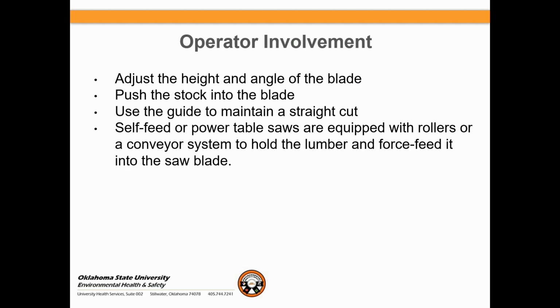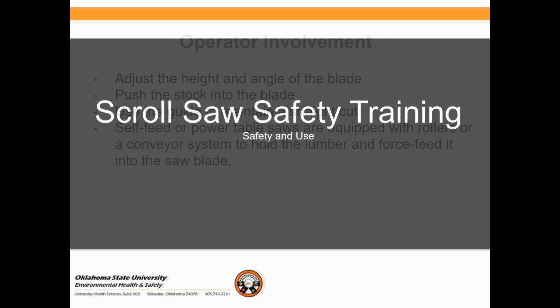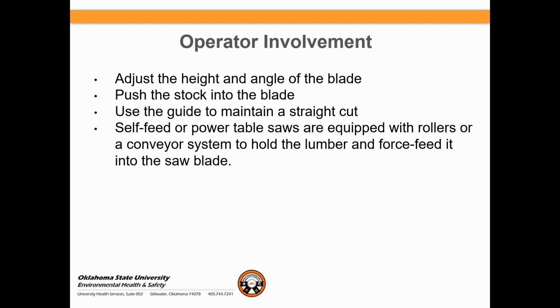Operator involvement: adjust the height and the angle of the blade. Push the stock into the blade. Use the guide to maintain a straight cut. Self-feed or power table saws are equipped with rollers or a conveyor system. Hold the lumber and also force feed it into the saw blade itself. Sounds kind of almost like a mechanism of some type that they're actually installing on the saws themselves.